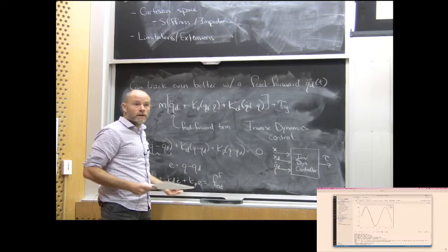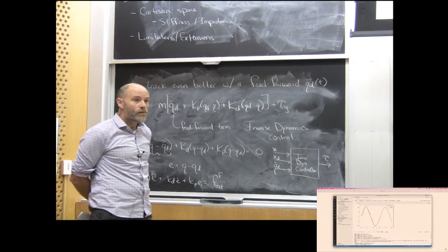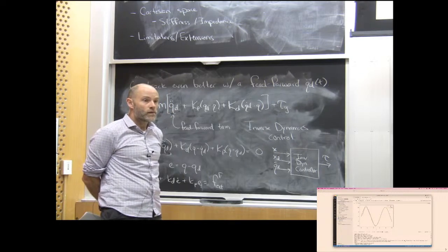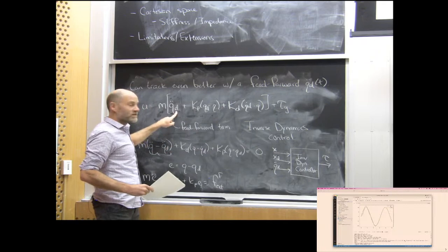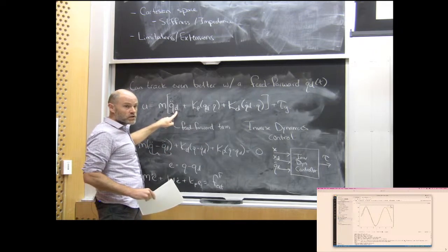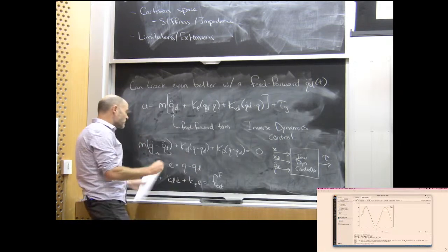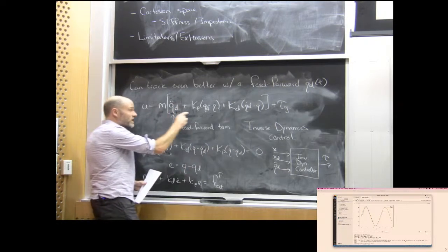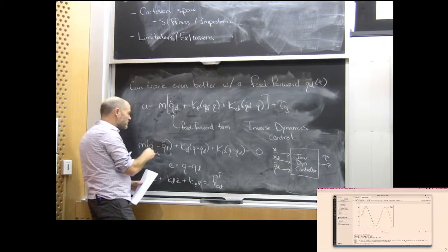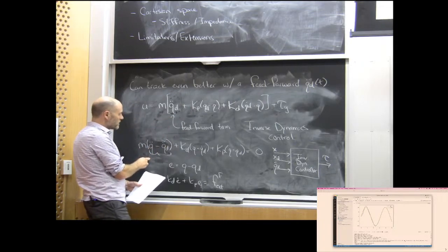Yeah? Good, okay. In reality, what sensor do we use to get Q double dot? Do we use a numerical method from positions, or do we have a sensor? Again, this is Q double dot desired. Yeah, but like the next equation. Good, that's a great question. This is me analyzing the closed loop system. This is the controller that I implement. This is what I have to type in. The result of combining my controller with physics is something that uses Q double dot because physics uses Q double dot. But I don't have to implement that.